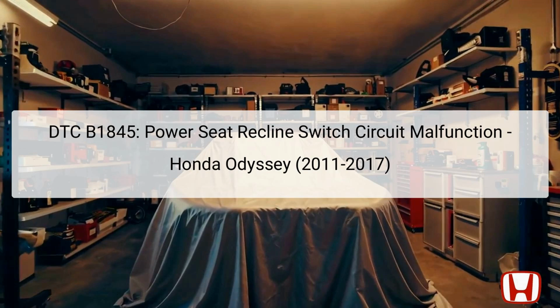Located on the side of the driver's seat, it's connected to the power seat control unit, which manages various power seat functions. Diagnosis begins with pinpointing whether the switch is communicating correctly with the control unit. If the control unit is malfunctioning, it can obstruct the signal necessary for seat adjustments. This procedure will involve a series of tests to determine where the breakdown in communication or function occurs.